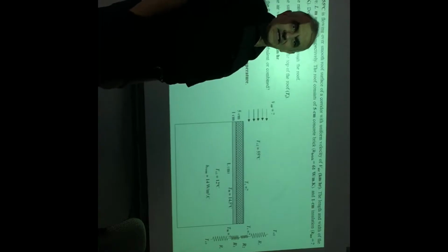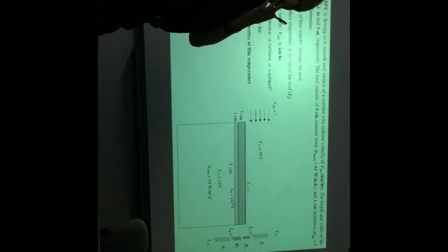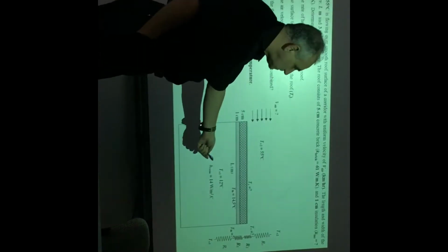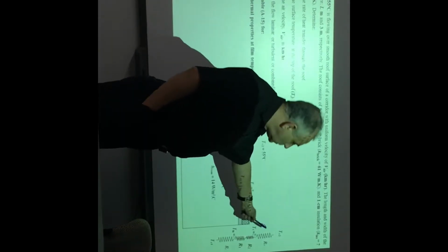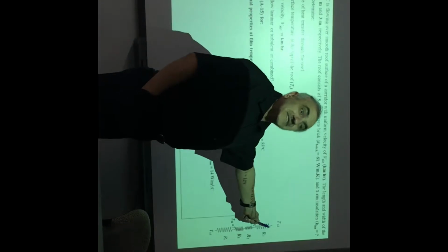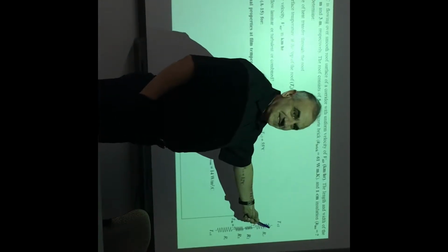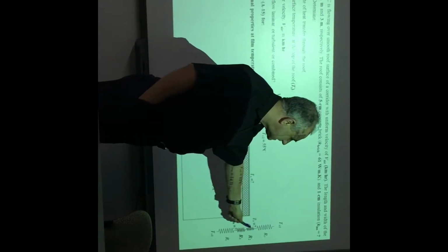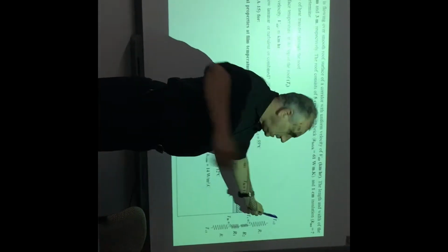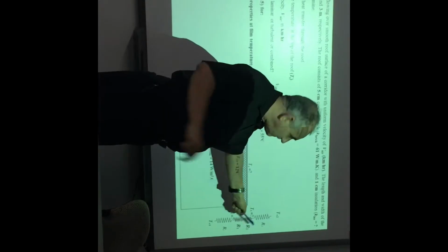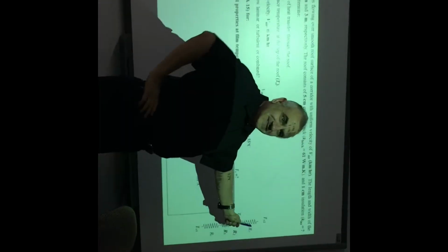Doctor, with T fluid 1 or with T fluid 2? As you wish. With T fluid 1, you can apply the bottom resistance. With T fluid 2, you have to apply the outside resistance, which is missing. So you have no way to calculate it from outside, because T fluid 2 is known, minus T surface, unknown, divided by the resistance, and the resistance is unknown.